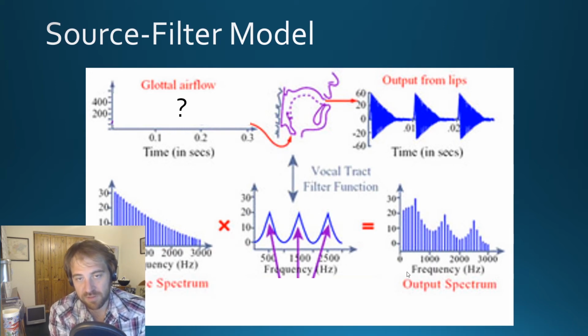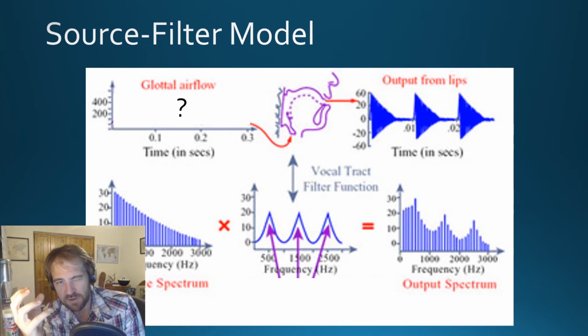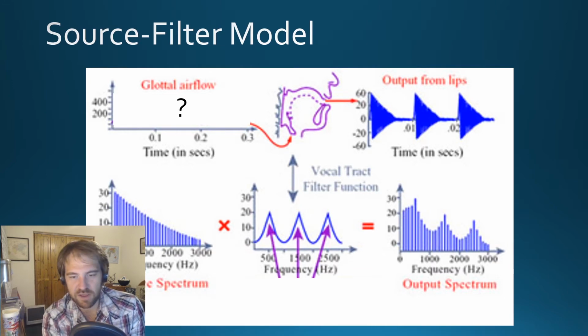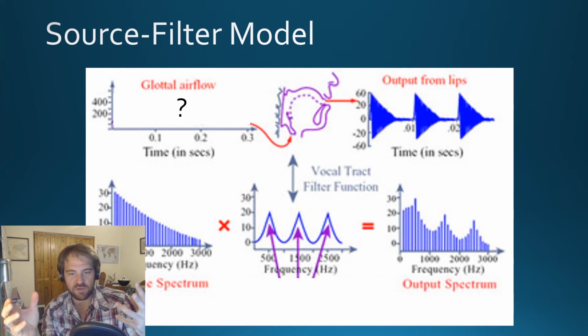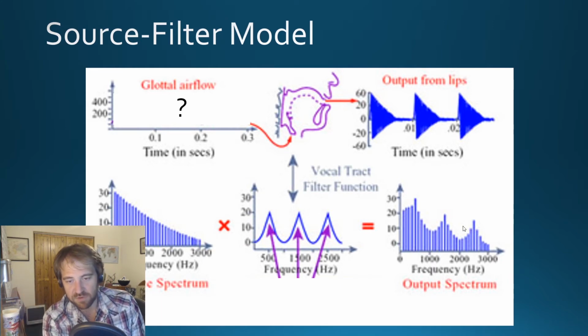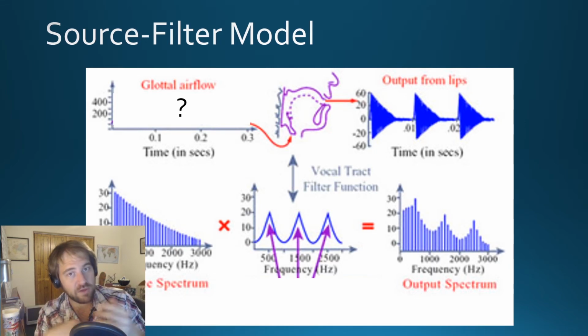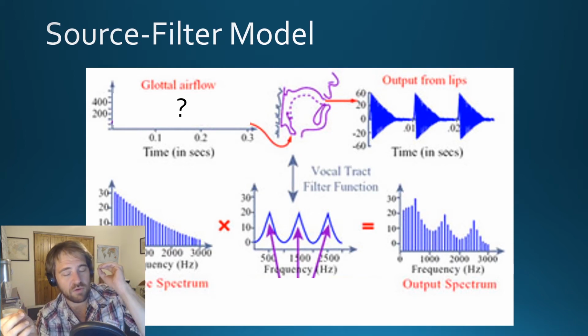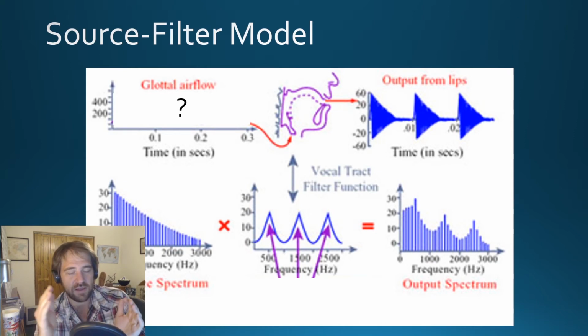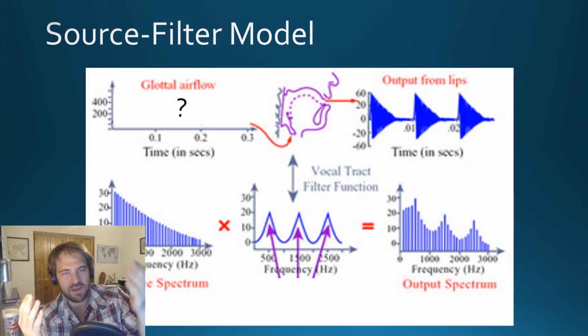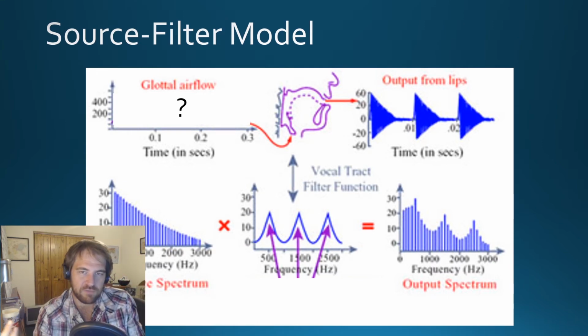And this is what we end up with when we're recording. And we can impute what the filter might look like in this case. We could kind of draw an envelope on top of this, like that, and get an idea of what the filter is. Now, of course, it might not be exactly centered. The peak of that filter might be between these two lines instead of on top of this line. It just could be. We don't exactly know what the filter looks like because the filter can only accentuate or dampen frequencies that are present. So if we're not giving it the exact resonant frequency, we don't know exactly where the peak is. If our fundamental frequency isn't in harmonic alignment with the resonant frequency, we're not going to see the exact perfect resonant frequency. But we can get a good idea of where it is.